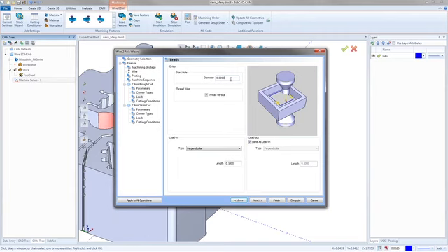We're going to start a 1/4 inch off that radius, off the center there. We're going to move it a 1/4 inch over and then start cutting. So we're going to ignore whatever diameter hole you tell us you put in here, especially when we're doing the coreless cuts.